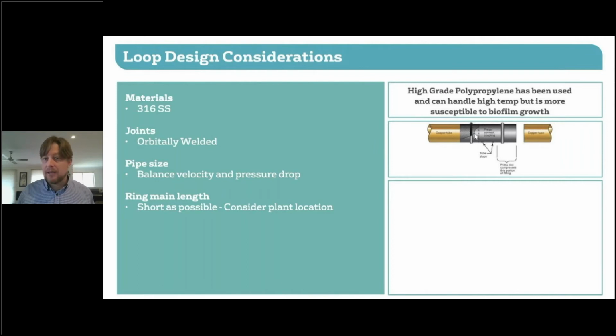It also happens to be up against the O-ring, which is obviously a weak point where you can get some minute bits of air entering the system, which can bring bacteria with it. Remember, especially with the hot water sanitisation, you are heating and cooling the water regularly, which means you're getting expansion and contraction of your pipe. So getting minute bits of air in through an O-ring is certainly a possibility. Though heat soak can help to kill off bacteria in these areas, it is a risk point, which is